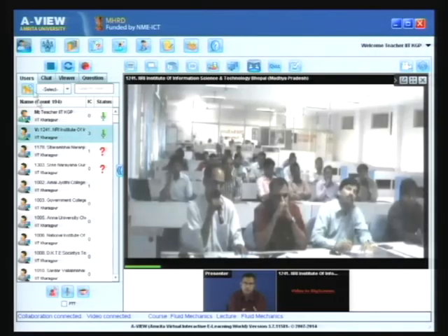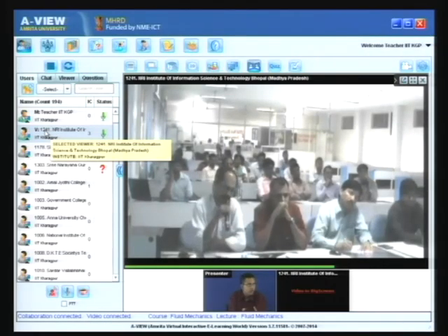So dp/dx has to be positive, but what positive value is necessary? If dp/dx is negative, there will be no boundary layer separation, but if dp/dx is positive, then depending on the flow configuration, there is no unique answer to this. Depending on the flow configuration, there will be a particular dp/dx for which the resistance effect is so strong that there is boundary layer separation.